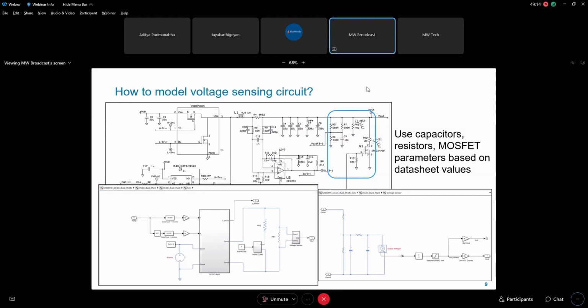For the voltage feedback circuit, the voltage we are looking at for feedback is the voltage across the resistor PR1. Again, here you can see capacitors and resistors highlighted in the schematic, modeled in Simulink using Simscape Electrical in the model snapshot shown below. In this scenario, you may have to add the additional gain introduced by the ADC for sampling the voltage. One thing to note here is that the kit has an additional provision to turn the active load on and off using the MOSFET switch Q1. This is also modeled in Simulink.